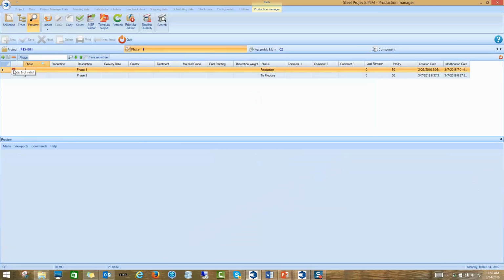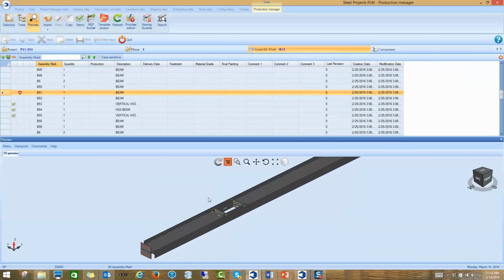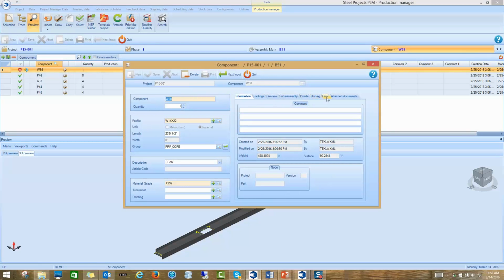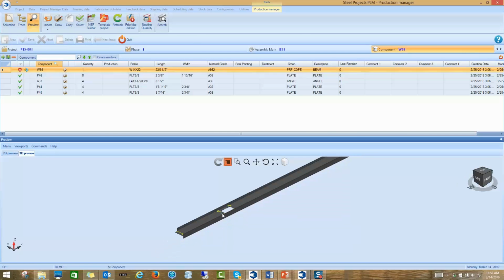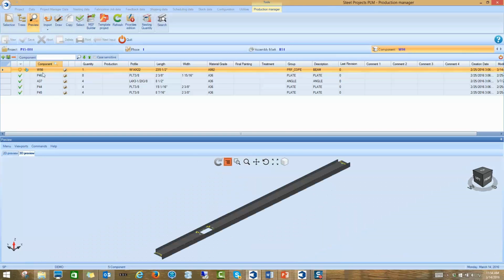inside the system. If you look here, there's an error. You can see a little shield there that says there's a problem. If we go and look at what that problem is, because we've got this intelligent data, we're able to drill down into that piece and find out what the problem is. And when we double click on that piece, we open the error that's occurred, and what we find here is that there's a piece mark that's come through from the detailing system that actually can't be applied in fabrication, in the manufacturing process. So we highlight these kinds of things, we highlight lots of other things that check what the detailers have been doing. And then we can either choose to fix that problem or send it back to the detailer or whatever we need to do with it.